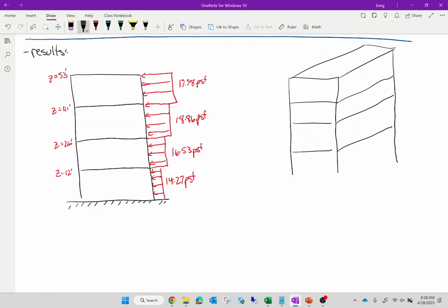Let's say that the building has a length of 120 feet this way. I'm just making that up. So maybe there's a brace frame on this side of the building, a brace frame on that side of the building. Half the load goes here, half the load goes there, apply tributary width, start analyzing accordingly. So, does that make sense?